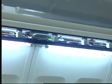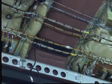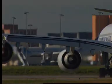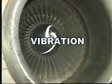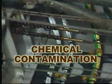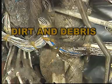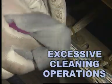A correct installation minimizes wiring degradation. The following items are considered principal causes of wiring degradation and should be used to help focus maintenance programs. Vibration, moisture areas, water, snow, etc. in areas such as swamp, severe weather and moisture prone, chemical contamination, heat, dirt and debris, indirect damage, excessive cleaning operations.